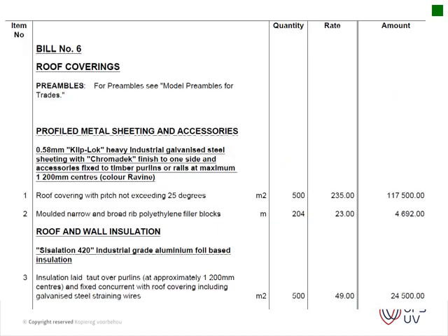Then our bills of quantities. Very important to note is that we've got bills of quantities. So our bills of quantities comprise many bills divided into trades. So now you've got your trade of earthworks, your trade of masonry, roof carpentry, which includes your roof construction, except if it's steel construction, then it will fall underneath structural steel, for instance. So the subcontractor would be a steel worker.